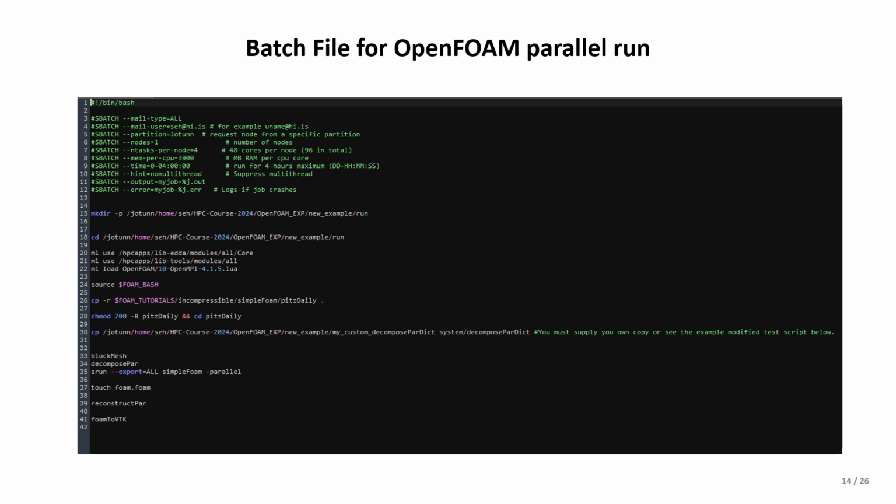Is starting with the meshing, create a mesh, and then decomposePar will make the decomposition of the domain of the problem, and then you can run the model with this parallel setup, and you can see the result. In part 2 of this lecture, we will have a practical example, and you will see how you can run OpenFOAM in parallel, and also visualize its result by ParaView.